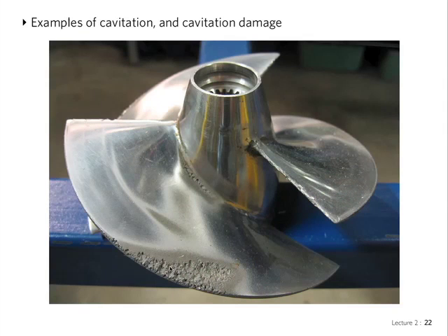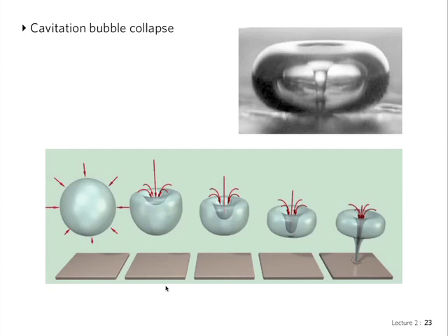All of this is cavitation damage on the propeller. And therefore designing propellers and so on to minimize cavitation, determining the right speeds of operation so that you can avoid cavitation and so on are going to be very important problems to solve as engineers if you are involved in this field of doing propellers. And I have here an explanation of what happens in just this cartoon. This one above here is an actual picture that was captured, and a very famous picture indeed, because it captures right the moment when this jet is created.